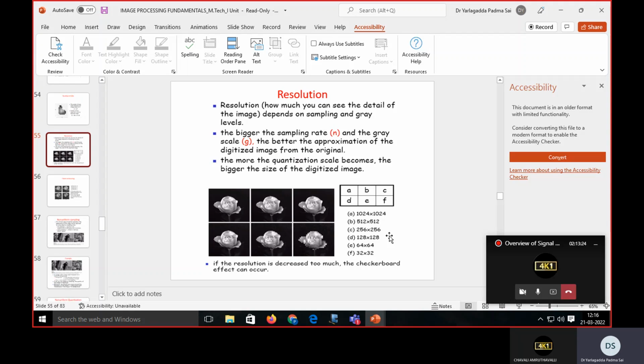For example, after enhancing, you have to transmit your image from a rural village to the city. In that case, you have to compress. There are various compression algorithms. Here you have arithmetic coding, similar to Huffman coding. You have some other techniques in image processing. In digital communication, you studied Shannon-Fano coding and Huffman coding. In addition to that, here you have arithmetic coding. All these codings come under source coding.